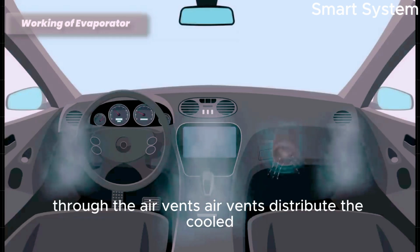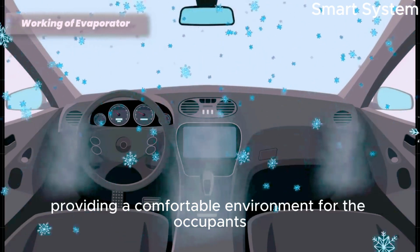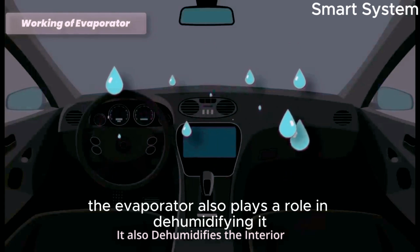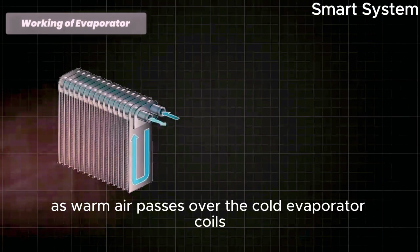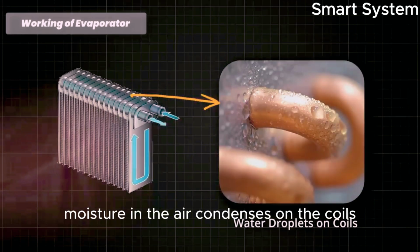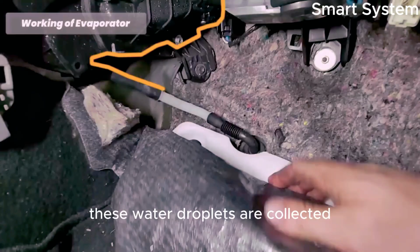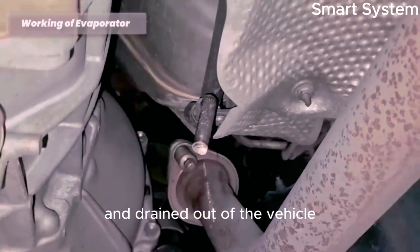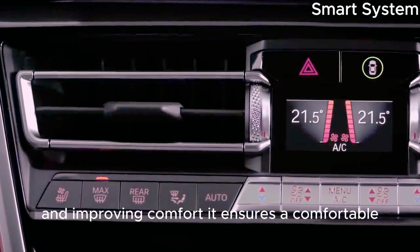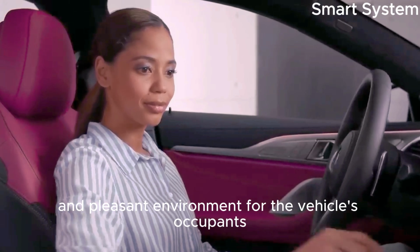Air vents distribute the cooled air throughout the vehicle's cabin, providing a comfortable environment for the occupants. In addition to cooling the air, the evaporator also plays a role in dehumidifying it. As warm air passes over the cold evaporator coils, moisture in the air condenses on the coils, forming water droplets. These water droplets are collected and drained out of the vehicle, reducing the humidity level inside the cabin and improving comfort. It ensures a comfortable, cool, and pleasant environment for the vehicle's occupants.